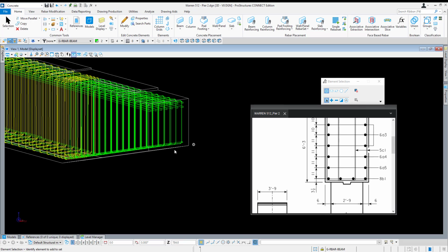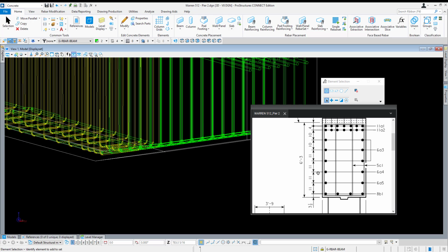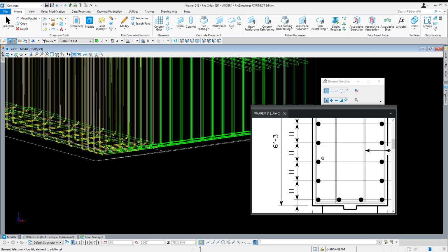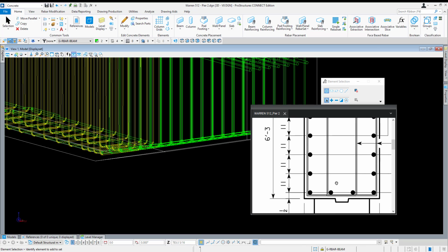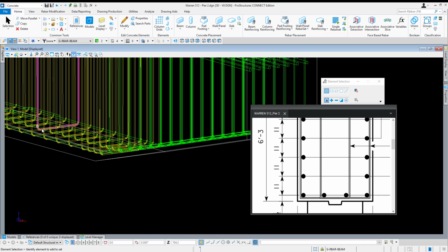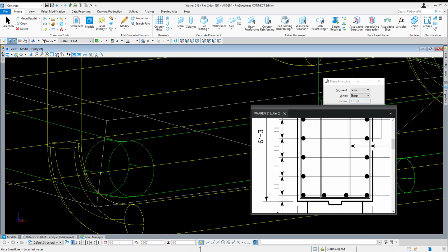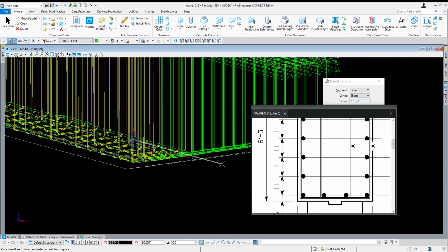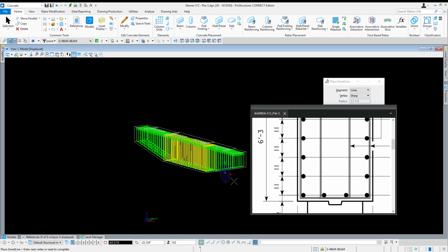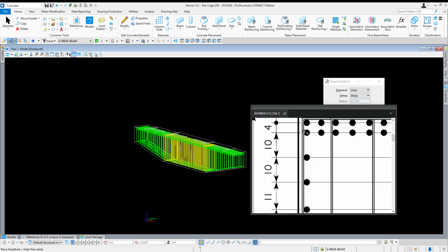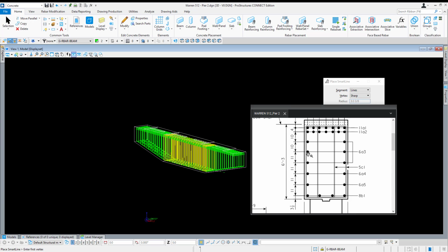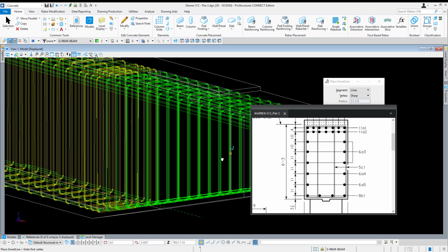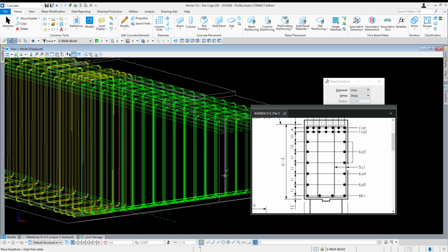Okay. So now, what I'm going to do is using this sketch here as a kind of point of reference. I need that first bar to be 11 inches from my last bottom bar. So there's the center of my last bottom bar. Go to front. Go up 11 inches. So that's my first bar. And then basically from there all the way up to the last set, it's going to be 11 inches. It looks like it switches to 10 inches. I'm assuming where these bars are able to extend all the way into the full length of the beam.